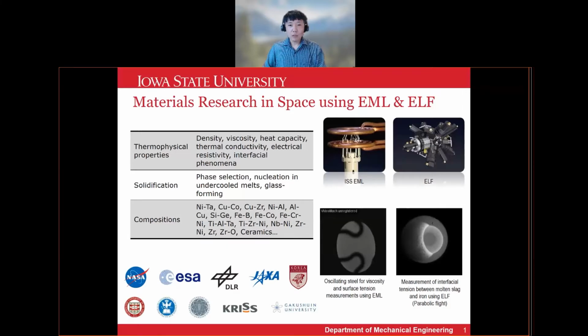Measuring accurate thermophysical properties is not only an important task itself, but provides critical parameters for the studies I just mentioned. For instance, we are interested in the influence of the melt convection and the phase selection of various alloys during solidification. In order to characterize the flow in a molten sample, we developed and experimentally validated computational fluid dynamic models which require thermophysical properties such as density, viscosity, and surface tension.